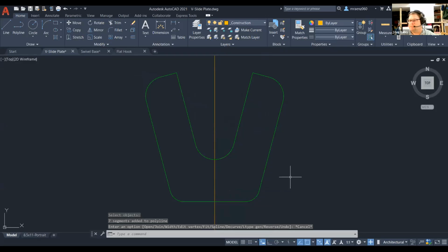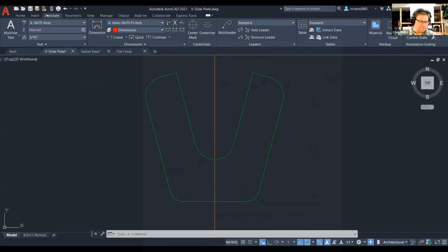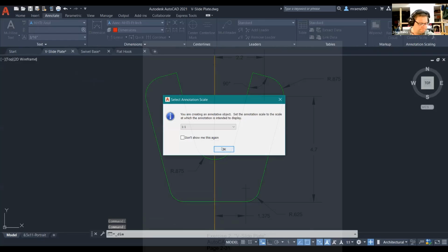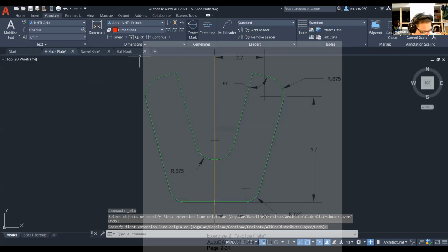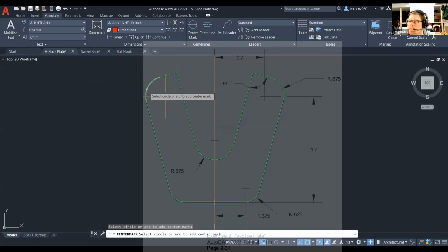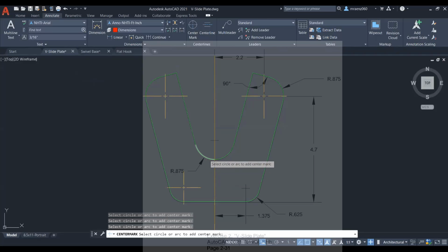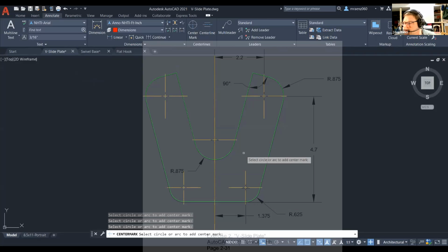Perfect. All right, Michelle, what I'd like you to do is go ahead and just do some rough dimensions, and let's see how close we got it. Okay. Should I keep it 1-to-1? It's fine. It's just in model space, and we don't need the dimensions for the homeworks. So let's see the 2.2 dimension. So you nuked your center marks. I'd put those back. It's all in construction now, but that's okay. And frankly, that's where it belongs. The center marks belong on the construction layer.